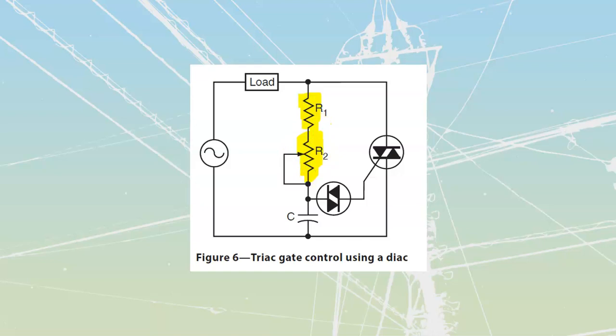This is very commonly done when we are building industrial controls, because it's what we call idiot proofing. Okay, customer malfunctions is the nicer way to write it up when you're filling out a work order. But a customer malfunction is really where somebody just does something and they wreck it, and we try to prevent that. And so instead of having just a rheostat, if I only have a rheostat inside here, there's a chance that the customer could turn it all the way down to 0 ohms.